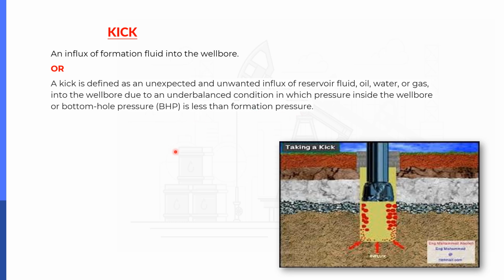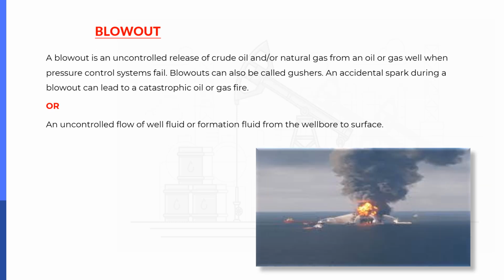It means the bottom hole pressure, which is maintained by the hydrostatic element, that is mud, is less than the formation pressure. At that time the kick comes to the wellbore. And again, if the kick is not controlled, it will turn into a blowout.